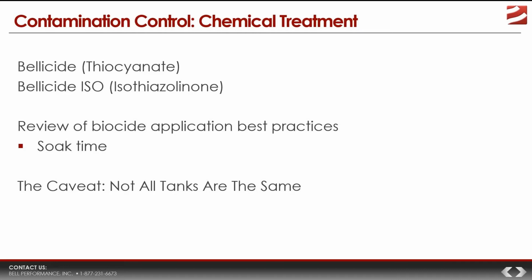again, because of certain factors, you're going to have to treat a tank a second time to ensure that the problem is wiped out. And a good fuel microbiologist will say, well, of course you will. You just can't predict with 100% certainty that this effect is going to happen 100% every single time. Life just does not work that way. Not all tanks are the same. Not all contamination levels are the same. That's a big thing. You may have to use more biocide in a heavily contaminated system.